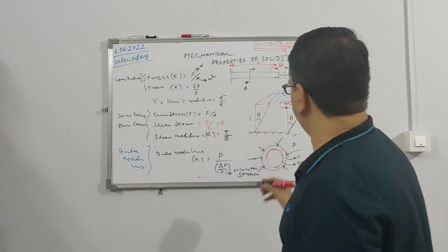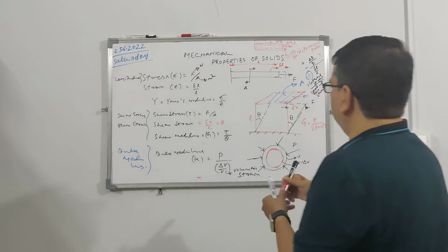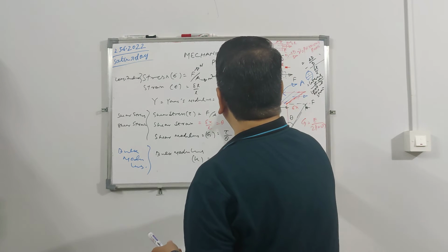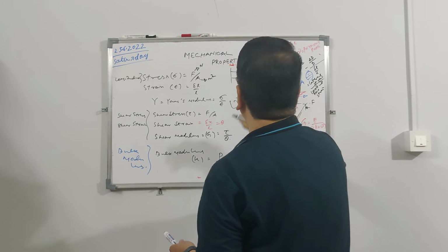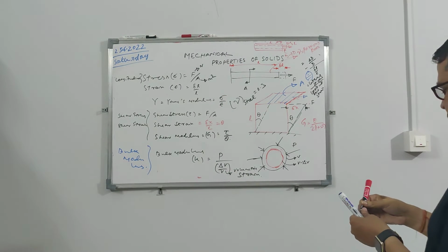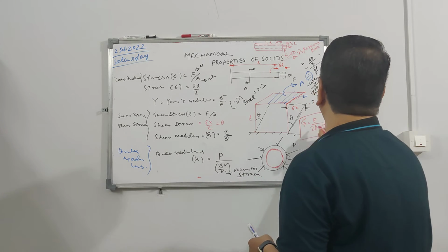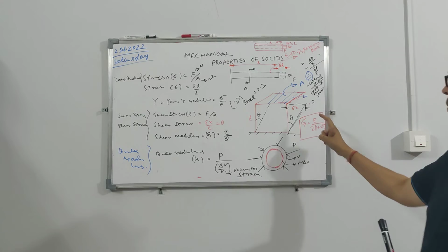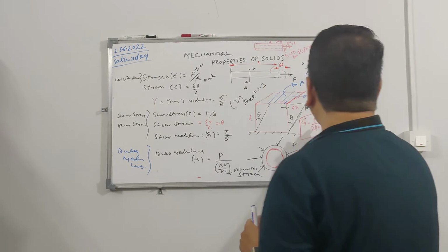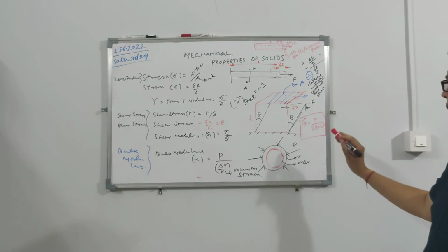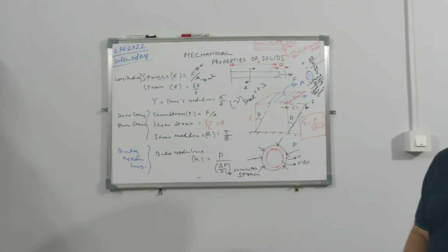So this is Poisson's ratio. So there is this Poisson's ratio for steel. Mu, Poisson's ratio for steel, is something around 0.3 or whatever. So this rigidity modulus is related to Young's modulus by this. So rigidity modulus is always less than Young's modulus. If you put 0.3 here, it will be 1.3. So 1.3 into 2, so E divided by 2.6.